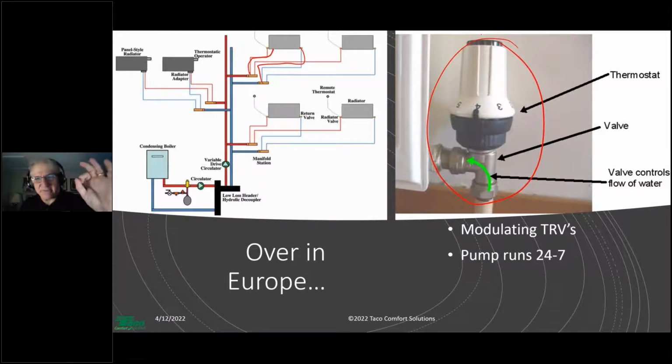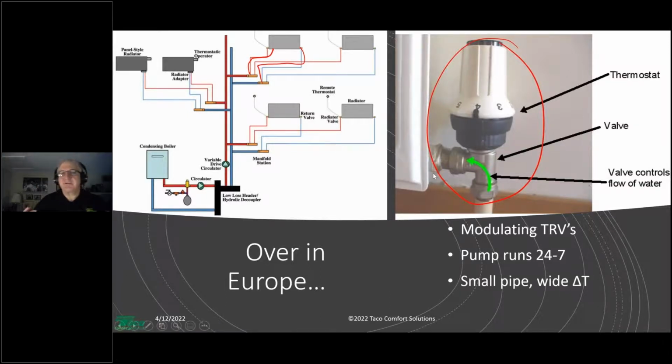It could be 14 millimeter PEX in European examples. That's still going to have a relatively high head loss. So the worst case head loss radiator might have, relatively speaking, a high loss. So for that reason, we have low flow, high head, steep curve circulators for your traditional European style systems. That's why a European circulator will traditionally be a lower flow, higher head, steeper curve pump.